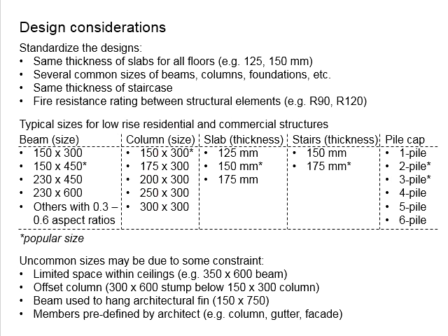This is provided that you have to abide by the proposed sections given by the architectural drawing. There are proposed columns. You can follow the size given by the architect. If you wish to enlarge the column, you will require consent from the architect. Especially the exposed column, that means the columns not hiding in the wall, it will be considered a part of the aesthetic view of the structure. Sometimes the architect purposely has those exposed to fit their design. You are recommended to use the exact same sections as proposed by the architect.